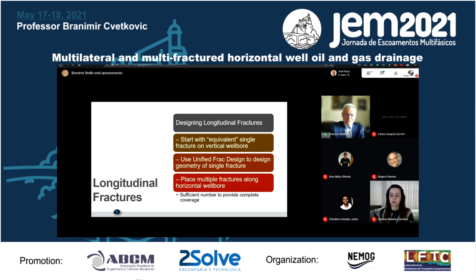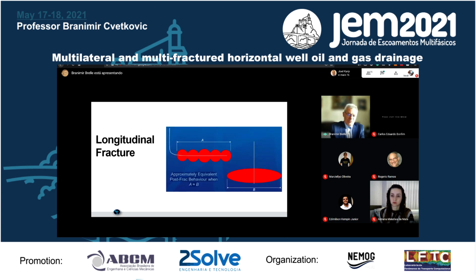But definitely you have to know why you are doing fracturing. Instead of having, in this case, 5 wells with one longitudinal fracture each, you decide to make one long horizontal well, and along it I create 5 transversal fractures.